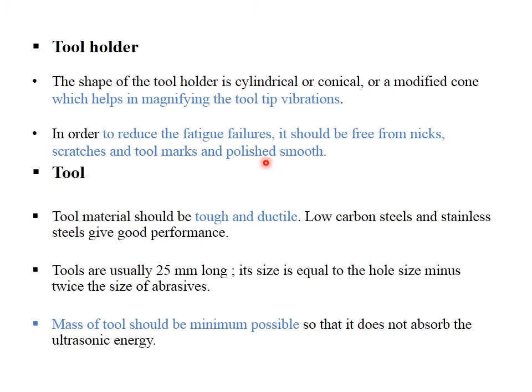Now what is the reason? Because this tool holder translates ultrasonic waves of high frequency, so there is a huge, intense translatory motion happening in milliseconds. If a crack develops in the tool holder, then after a certain time there will be a fatigue failure of the tool holder. So you have to be sure that the tool holder is free from any scratch, mark, or micro crack, and the best way is to have a polished, smooth surface.